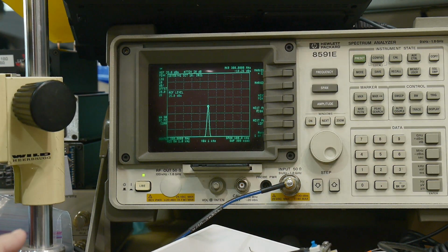They're not really measuring quite right. We're at 25 dBm reference of 25. Oh wait, let's see. Not minus 18. I'm sorry, I'm measuring minus 18. So a little bit off. Let's do minus 30. All right, and we're measuring minus 31. I guess it's okay. Minus 40. And minus 38. So it won't go anything below minus 38.